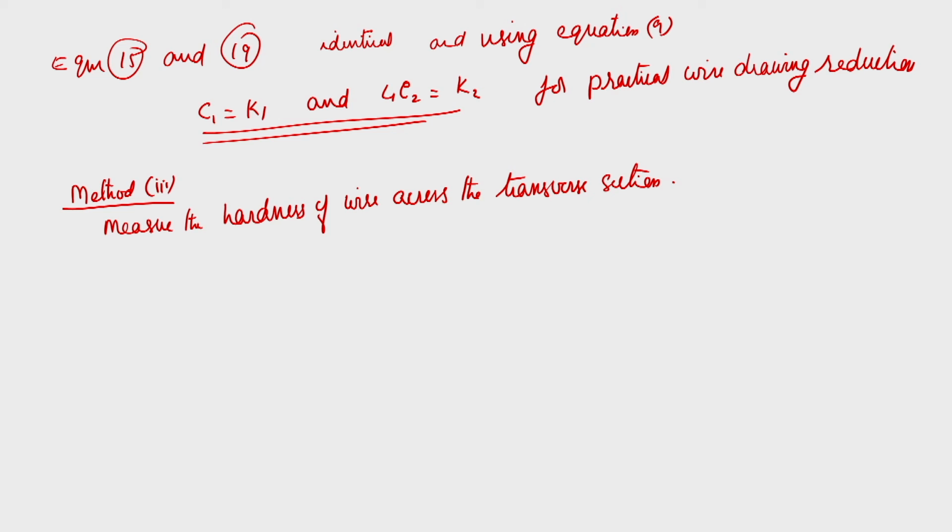But before that, you homogeneously deform the material, do a tensile test, maybe for some reduction of 5%, 10%, 20%, 30%, 40%, like that for different reductions; you get a series of experiments done. Because it is tensile pulling, you can easily get the equivalent strain.